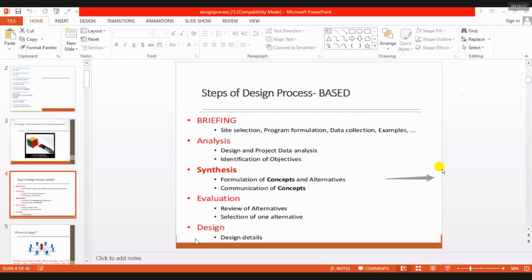Okay, the term block plan. First of all, I will explain the term block plan with reference to the term bubble diagram. A bubble diagram is a freehand sketch of the spatial organization of spaces within the building, and the size of a bubble is relative to the standard size of that area. The spaces are organized according to their spatial relationship with one another. For example, placing bedrooms near one another, placing kitchen, drawing and dining near one another for their functionality. They build their relationship as well.